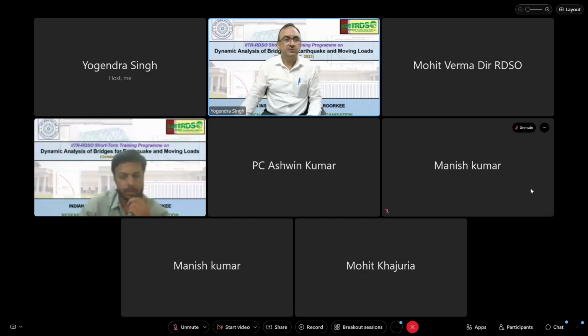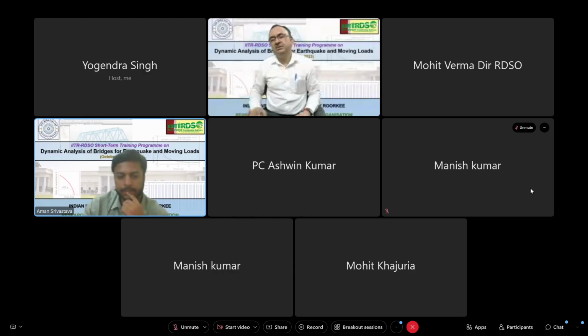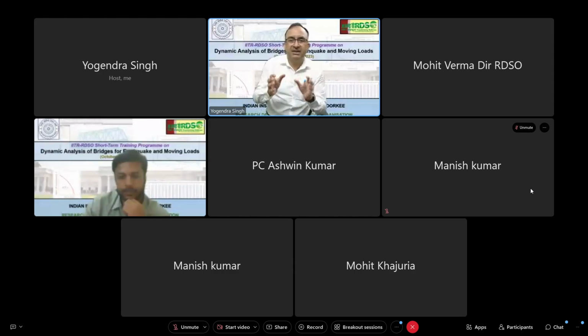Okay, sir. Mr. Suraj is asking, can you please explain the method for missing mass correction, as IS 1893-2016 also suggests the missing mass correction, but doesn't give any method on how to do it? Okay. So missing mass correction, what is this missing mass? Missing mass is that portion of the mass of the structure which you are not able to excite even with a sufficient number of modes.